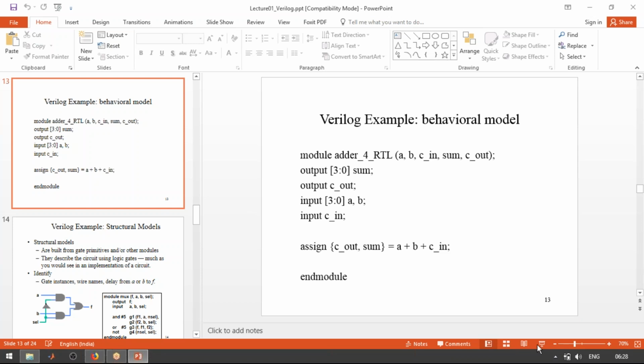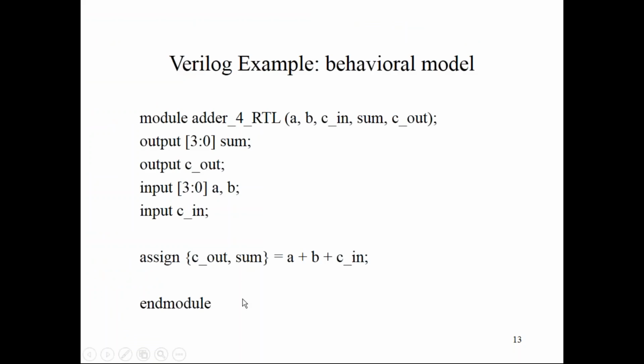Okay, fine. So in this way, we are interconnecting, or sorry, we are writing our module to define. Here, assign is a keyword. Using a Boolean logic expression, we are directly defining that module. We know our adder is an addition of all the bits, so A plus B plus C in, which is your carry input.